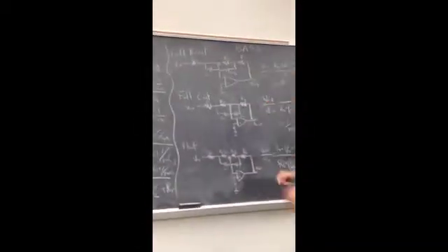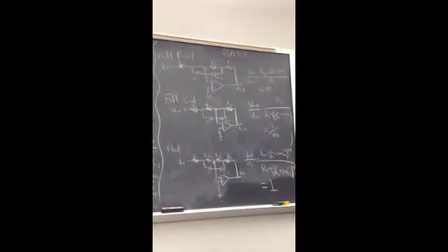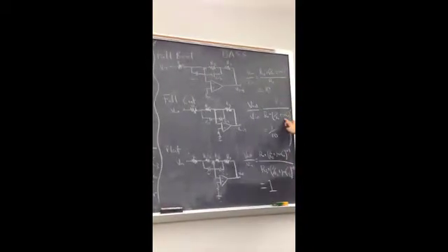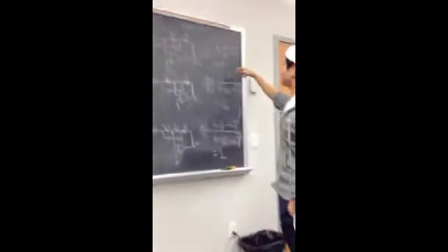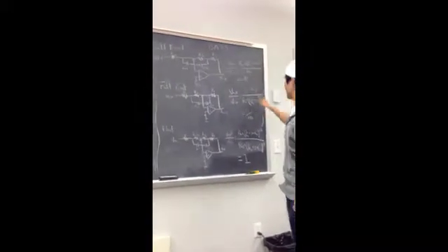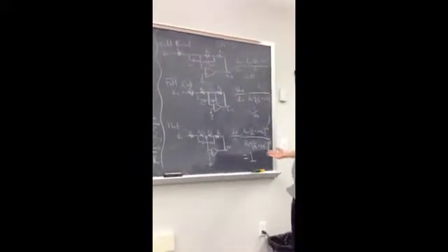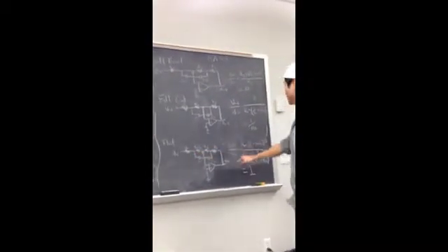resistor. And similarly, same logic over here for bass for accomplishing the 10, 1/10, and 1: for low frequencies, this value j omega C is practically 0. So again, we run into the scenario of a ratio of resistors. And if we pick the same capacitors and the same R1 and R3, then this will remain 1.